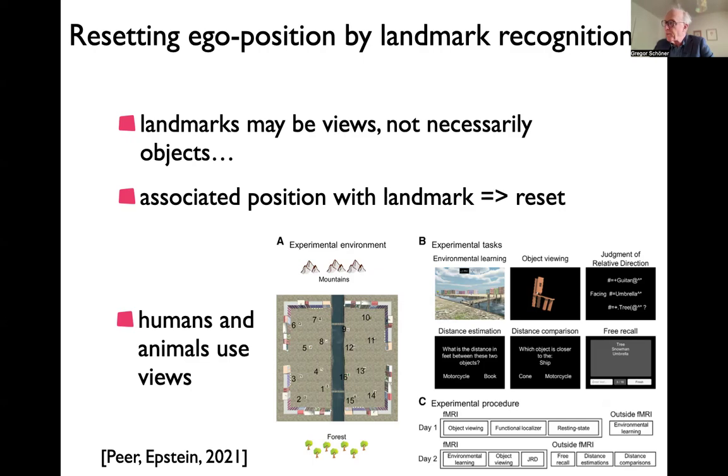That's the principle of how you use landmarks intermittently. For that, of course, you must have experienced that landmark before and associated some kind of location with it on the map. If it's an external map, you just take the entry in that external map as your new starting position. You reset your position estimate based on that, and also your orientation estimate.